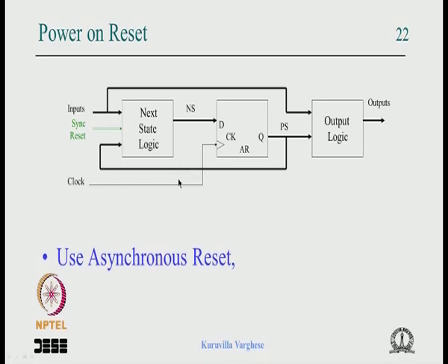We have also said, in tune with the kind of synthesis we are doing at the RTL level, that when given to a synthesis tool, you know that the reset has priority over all other inputs. It means that ultimately the circuit is nothing but a 2-to-1 multiplexer at this stage, with the reset as the select line.